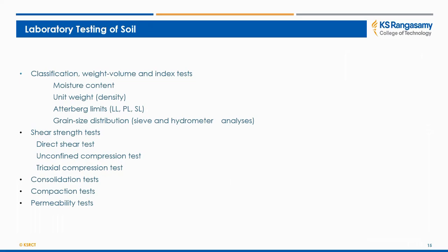For the shear strength tests, the first one is the direct shear test, which we conduct for cohesionless soil. The unconfined compression test and triaxial compression test are for cohesive soils. The consolidation test is normally conducted with readings at 24 hours and follows about 5 days. The consolidation test is normally used for the settlement of the foundation.